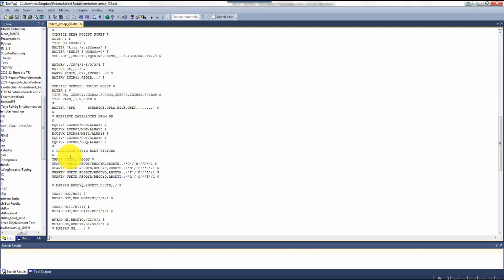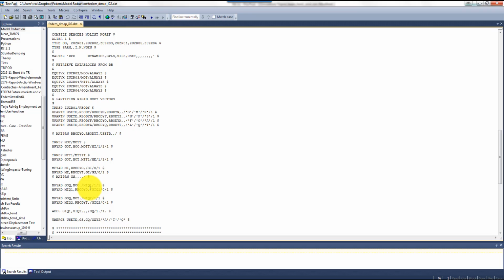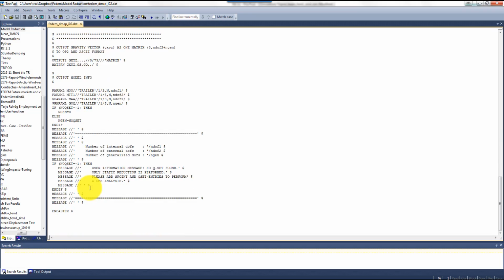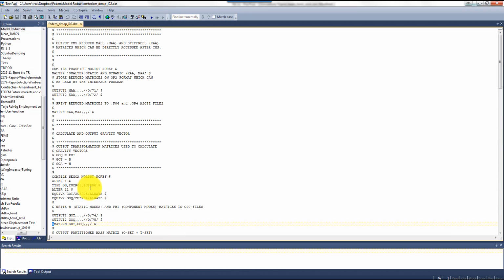What you need to do is to search in the DMAP documentation in Nastran. It's about 1800 pages of descriptions of user routines. And if you think you have found the routines that do the job for you, you can compile it with the list option to see the contents, and then you can add new commands or alter the execution of that routine. So that's how it works.